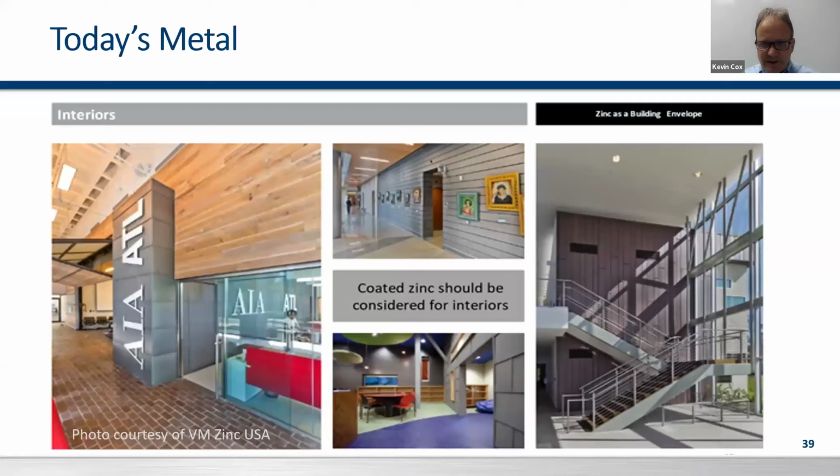Work with natural metals, zincs, very, very popular, especially in Europe. Gray in color, but we can do pigments to create different colors and finishes. The pigments aren't always very UV stable, so eventually zincs will usually patina back to gray. We can't really tell how quickly that's going to happen, just that it will happen. So it's just something that if you're working in zinc, you want to set the table.